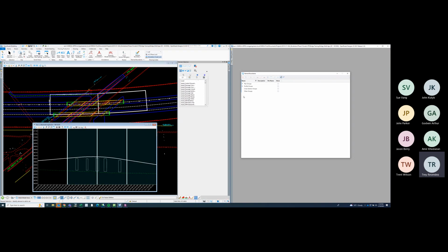So when you're cutting the sheets, you're going to want this dialog, and all I did was click this button here. You're going to want this toggled on, so you want this highlighted: show the create drawing dialog. Then come to your groups, click here on the group, and either right click and hit create plan profile drawing, or just click this button here. So I'm going to click on this one.